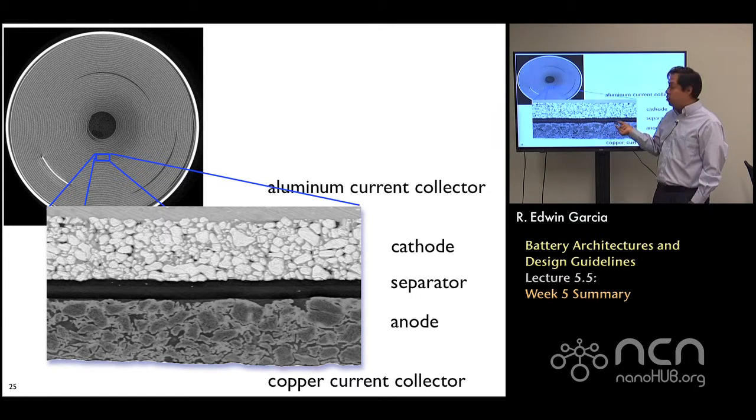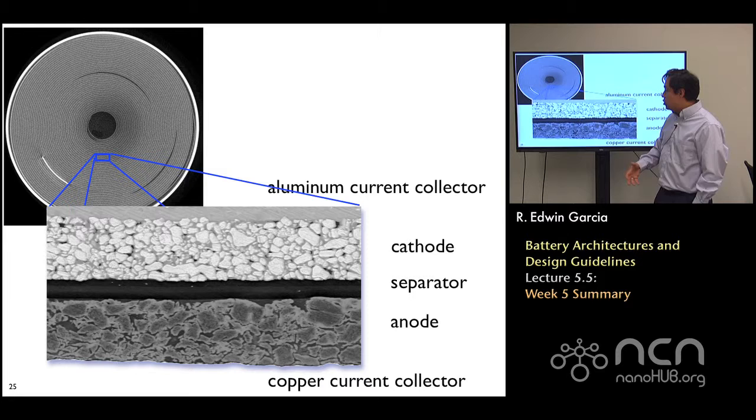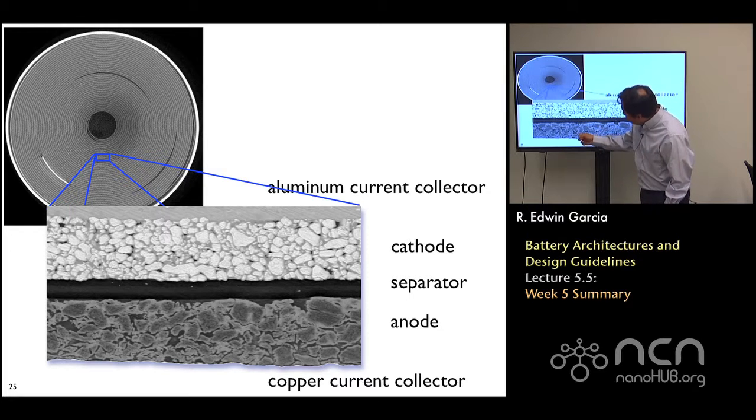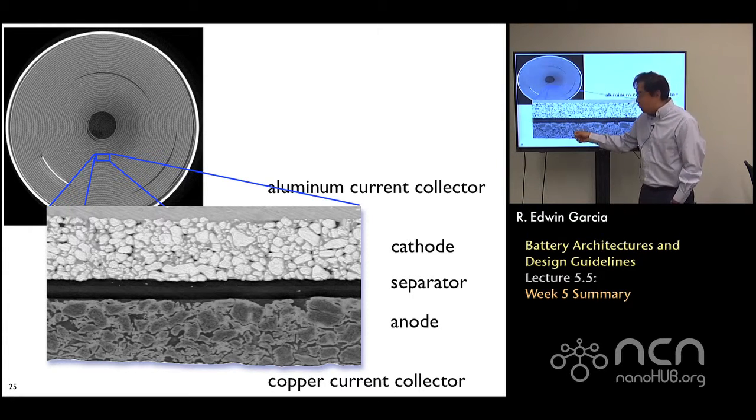This layer has to be very thin, and in this case it apparently has 3 internal layers, as a result of what people designed in order to maximize performance. And the anode itself gives the impression that it has been cycled several times, because of these flaky-like regions resulting from failure mechanisms.